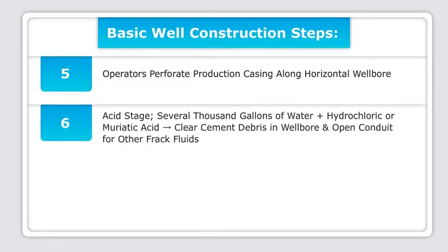6. Acid stage, consisting of several thousand gallons of water mixed with a diluted acid such as hydrochloric or muriatic acid. This serves to clear cement debris in the wellbore and provide an open conduit for other frac fluids by dissolving carbonate minerals and opening fractures near the wellbore.